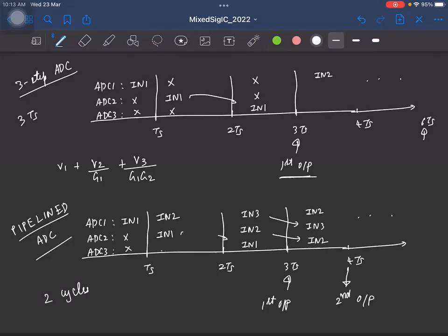Okay. And in most cases, it might be fine, but in some cases, this additional delay might not be tolerable. Can you think of an example or a place where delay cannot be tolerated? Some kind of a system where you can't tolerate any additional delays. Okay, real-time systems is fine. Someone said negative feedback systems, right? If you have a negative feedback system, the more delay you have, it will compromise the stability, right? So you might want to use an ADC in a big negative feedback system because you want to get an estimate of something and do some kind of a correction. In these cases, this latency might not be tolerable, but otherwise, in many cases, this might still be okay.